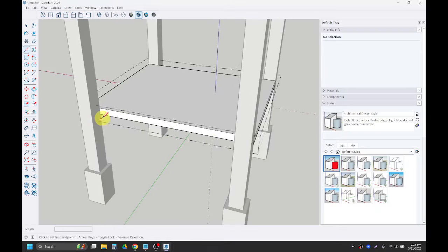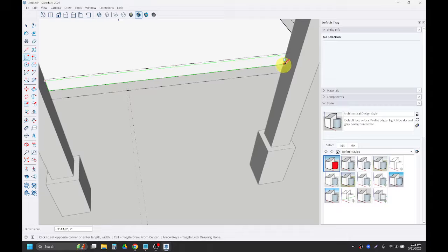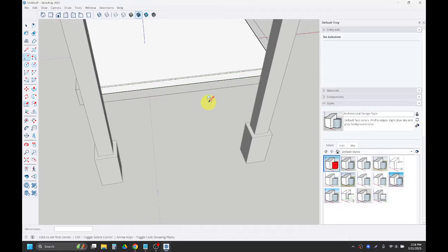I could also, on this side, use the rectangle tool instead of the line tool. So keyboard shortcut R to go from intersection to, let's see where intersection is. I want to make sure I'm on the right piece. And then push-pull just that face out for it. Then once I've got my platform all done, I'll hit my space bar and I'll double click outside of the group to end editing that group for it.